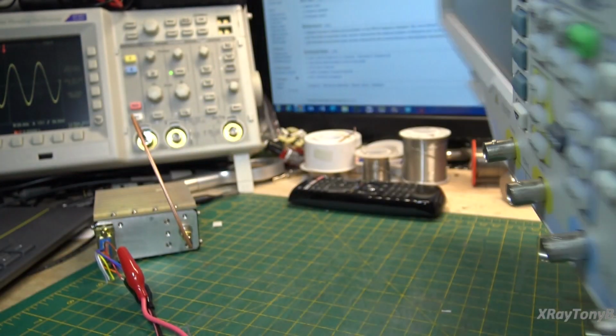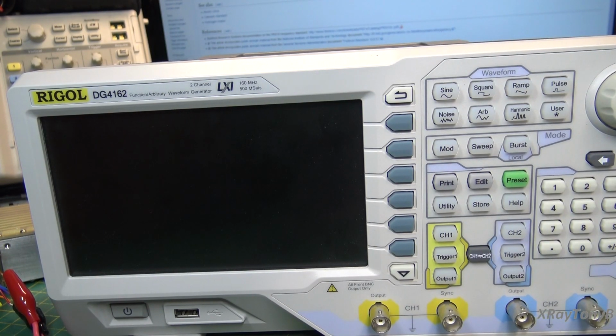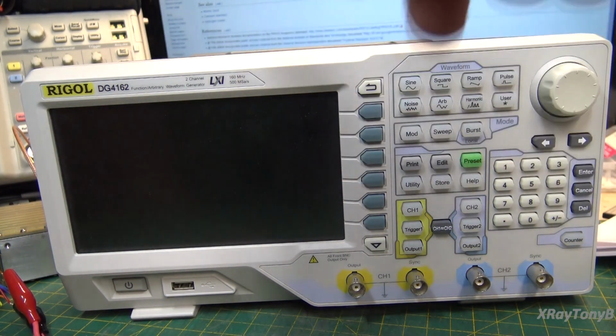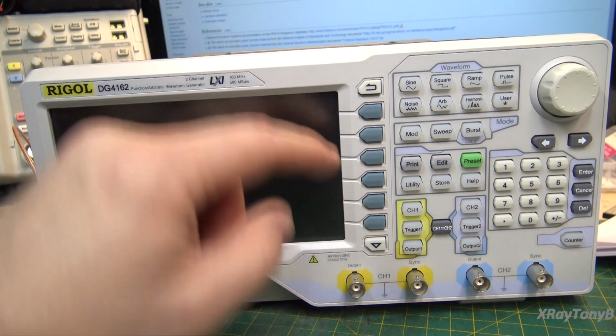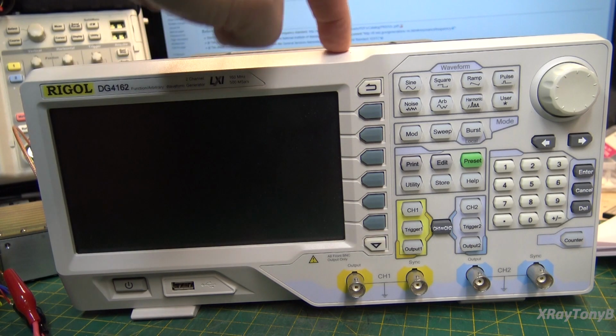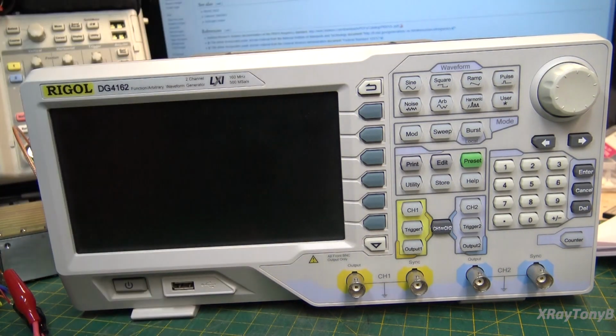So this uses a 10 megahertz frequency standard as its main clock to generate all the other frequencies that you select. All right, and you can output that 10 megahertz, and it can be a reference to have all of your other devices connected to the circuit tracking with it, so that they're all synchronized to that same frequency. Okay. So this can be a 10 megahertz reference. Although it's not highly accurate like a rubidium, it will work.